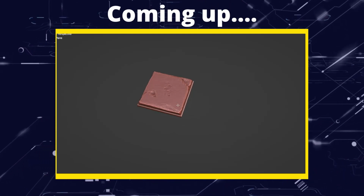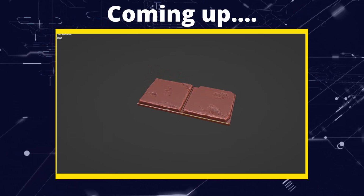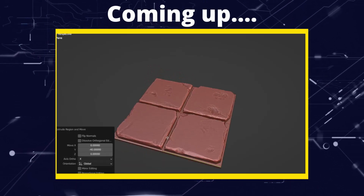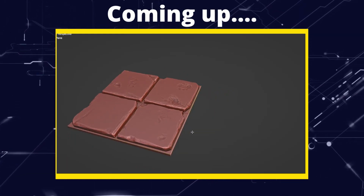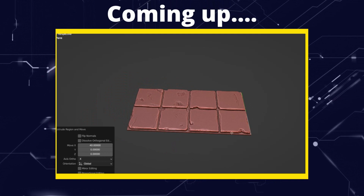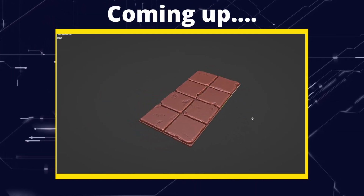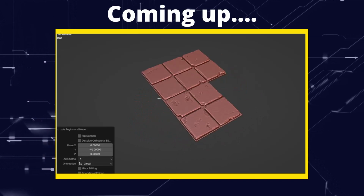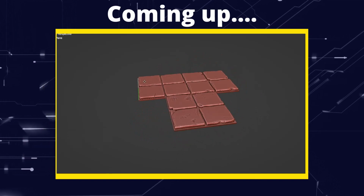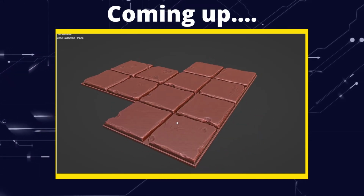So as you can see, we've got this single dungeon floor tile, and we can quite easily move this out and select edges to create a series of dungeon tiles. So we can do something, for example, like that. And then we've got our dungeon tile or our corridor sorted, or we could change that if we wanted into something like a T-junction and do something like that. So this will quickly generate these tiles, and then this will be 3D printable and something you can use for your dungeon exploring.